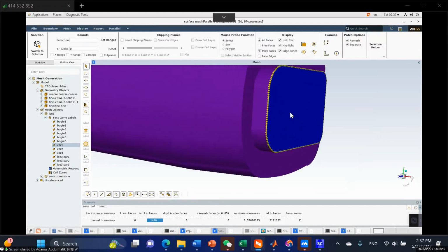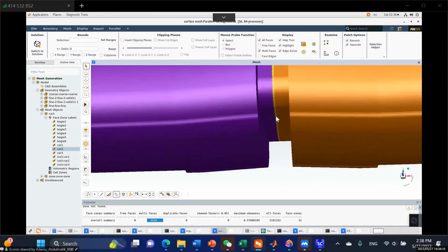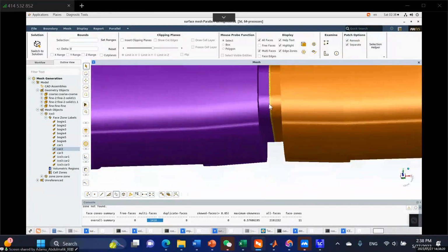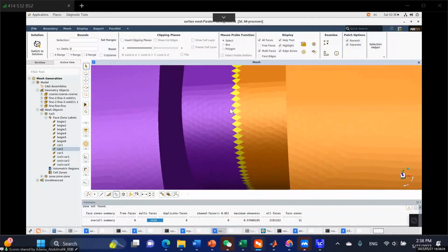Please, you cannot have a hidden face. For example, I also want to see car 2. So I come to this, click and come to the draw option. I will now press add geometry. Now you can see that face that I earlier showed, the face in the carriage gap.